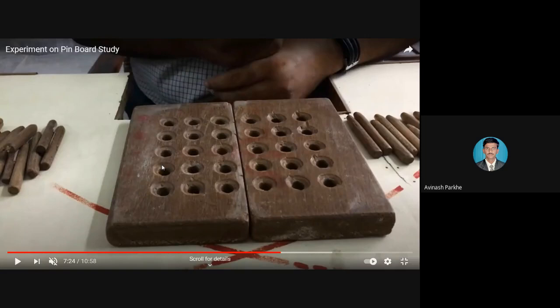Whenever I am inserting the pin in the hole, sometimes it will create fatigue or it will not be properly inserted. So to avoid such situations, I have made some modification at the top side of the hole. I have increased the diameter somewhat at the top side. So this is called a bevel hole. The structure is made like a bevel. So these holes are called bevel holes, and the previous holes in front of you are called straight holes.